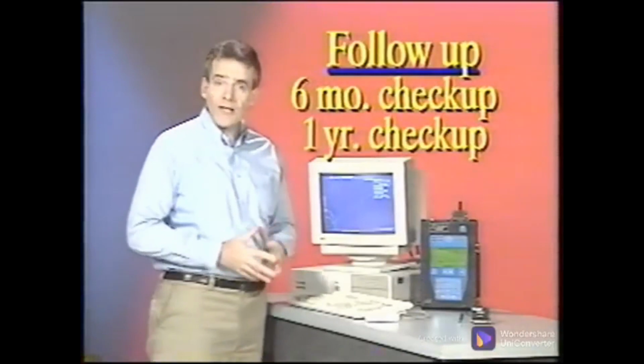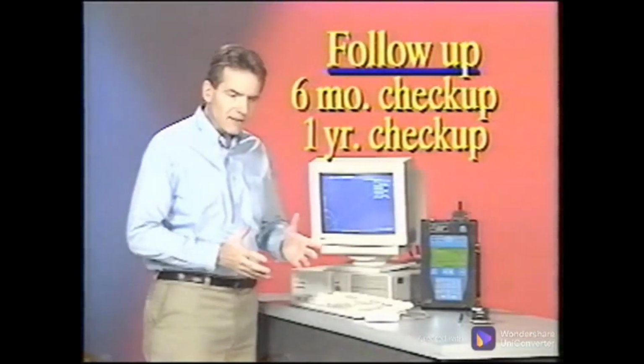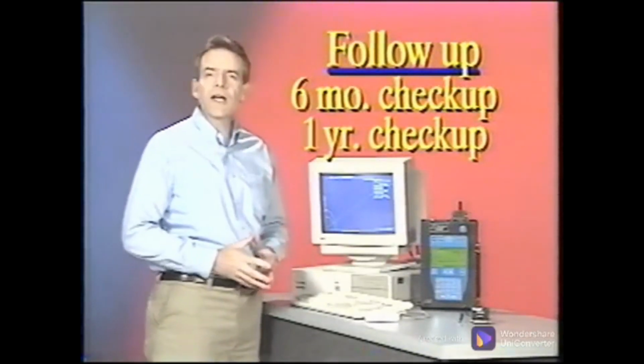Another follow-up is to recheck the alignment in 6 months, and if it is within tolerances, recheck it once a year. This is made easier with the laser and electromechanical systems because the alignment job can be stored in a computer database where it can be reloaded into the alignment analyzer at a later date. This speeds up the alignment process. Now only the machine distances and any new thermal growth information is required before measurements are taken.